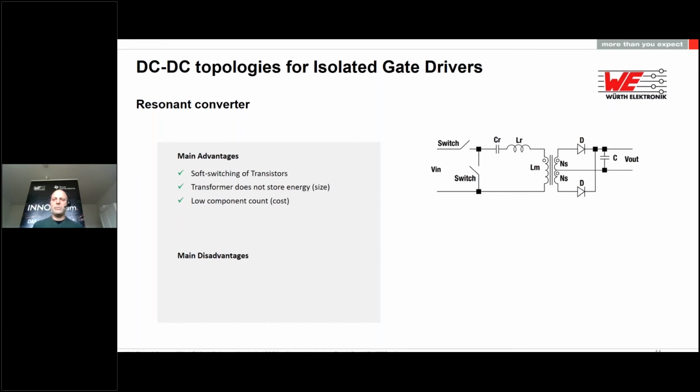But by minimizing the operating range of the LLC, like running in open loop, always at resonance, therefore fixed frequency and low voltages, DC-DC, it allows us to simplify the design, and then the remaining needed features could be integrated in a controller IC.